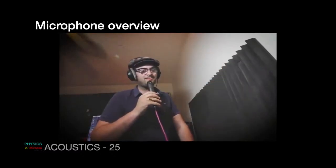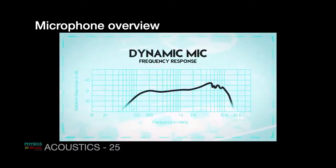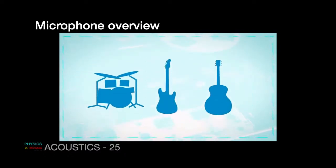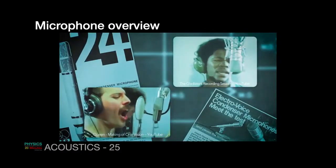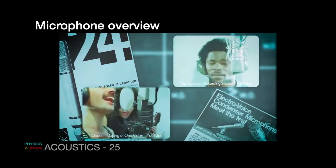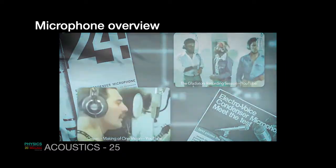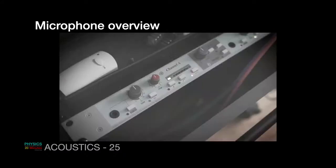Not bad at all. They don't have the crystal clear full bandwidth operation of condensers, but this is actually often a good thing, such as when you're recording certain types of drums, guitar amps, or other acoustic instruments. Condensers are good for vocals, generally somewhat fragile, and usually more expensive. They are known for their ability to capture fine detail. Condensers require some current to work. This is phantom power, which is commonly represented by a button or switch labeled as plus 48V.